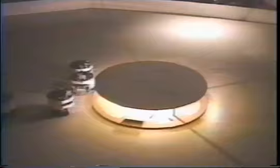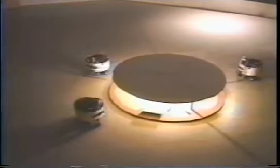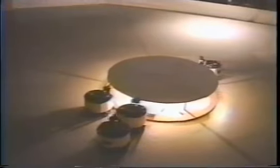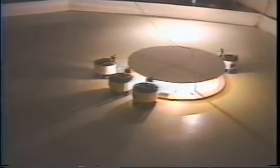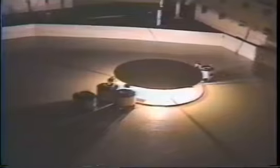Repositioning can and often does cause the robot to lose sight of the box, since the field of view of the box sensors are not omnidirectional. This results in the robot having to relocate the box and find a box side and determine the goal location. The box can be transported between different goal positions by sequencing the goal indicators.